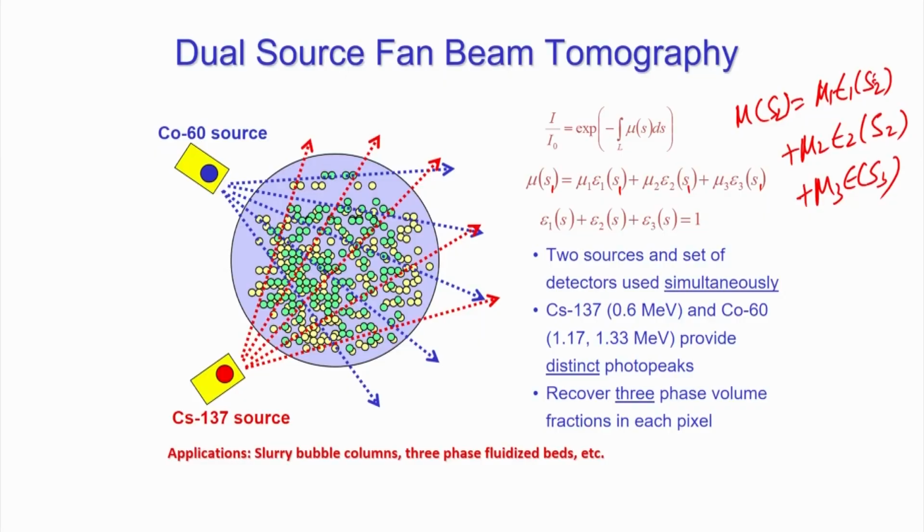Okay. So in gamma ray tomography or X-ray tomography you can achieve good spatial resolution but bad temporal resolution. In ECT you can achieve good temporal resolution, bad spatial resolution. MRI can fulfill both the job, but this is very costly, and therefore a combination of techniques is being proposed for measurement if you want to understand complete flow dynamics.